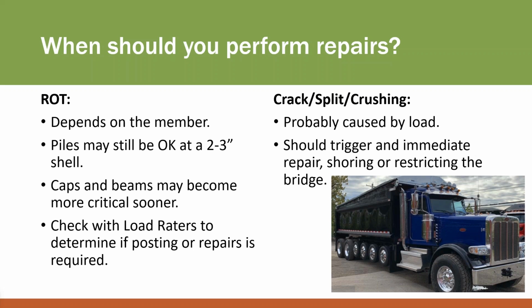But I really do blame this new fleet of trucks that are going across the country for disproportionately taking out timber bridges or causing some of these crack splits and crushing. So if you have a long span bridge, like a lot of our steel and concrete span bridges, then these trucks, even though they're really heavy in a short distance, it's not the end of the world. It can spread the load out.